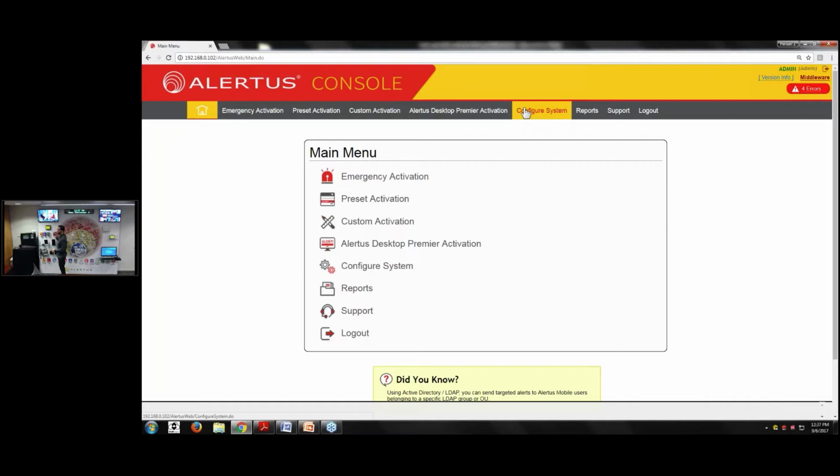You would go in, reset the fire pull station that was used, then you would reset the fire panel. The resetting of the fire panel would then, after it boots up, notice that there is no more alarm.